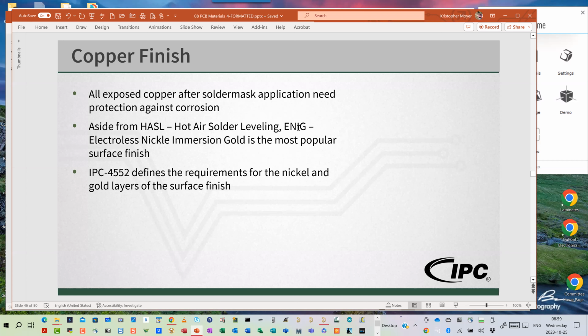Then between the nickel phosphorus and the gold, it adds a palladium, yet one more precious metal layer, and I get into that in my mil-aero class. It has to do with the intermetallic joint formation and structural integrity of the intermetallic crystalline growth layers between the nickel and gold. Nickel to gold is a good layer, but under certain conditions, it can fracture right along the nickel phosphorus to gold interface. So you make a second intermetallic bond, nickel to palladium, and then palladium to gold, so they get better structural strength out of those.